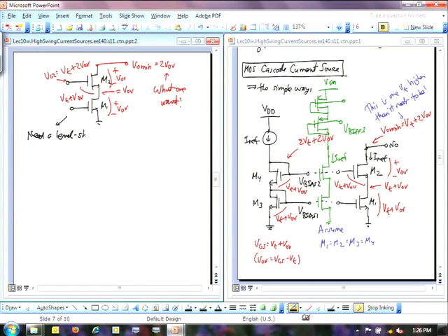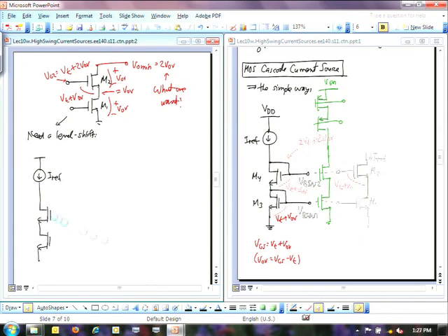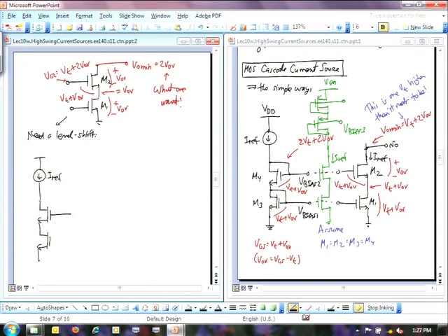So I'm going to start out with that circuit that I've already complained about, right? Because there may not be a better way to do this here, which means bias up these transistors such that they take on the voltages corresponding to the currents that are going through them. So I'm going to keep the diode connections of these things, because if you shove a current through a diode connected transistor, it automatically biases that thing up. Right? That's definitely one thing that we want.